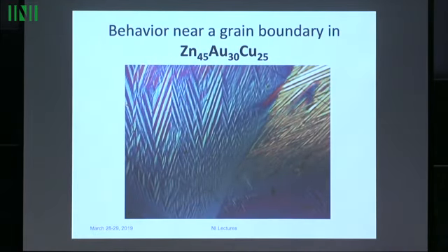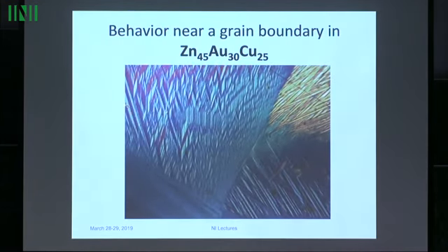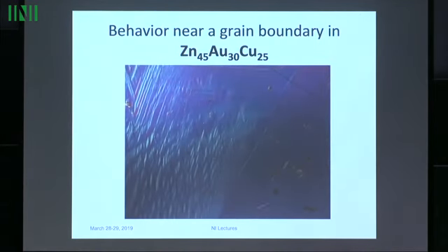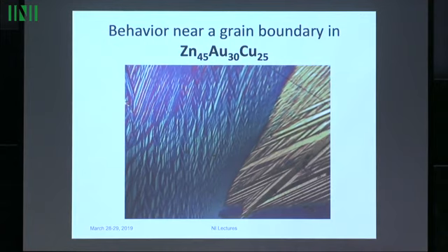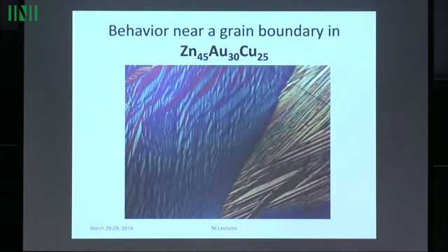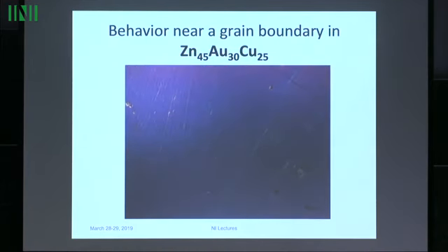First of all, you see every frame is going to be different. But the other thing you see is that it seems that the microstructure on one side of the grain boundary is uncorrelated from the microstructure on the other side. There's no obvious relation from the pictures between the microstructures on each side. Again, indicating there are just many, many choices, and indicates roughly that there's a very flat energy landscape.